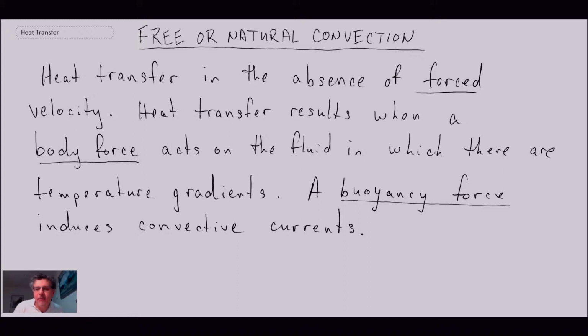So what we're looking at is convective heat transfer in the absence of any kind of forced velocity. We don't have a pump or a fan causing circulation in the fluid, and it is the body force within the fluid that is providing the mechanism of moving the fluid over the surface where we have the heat transfer taking place. And buoyancy is the body force that is driving it.